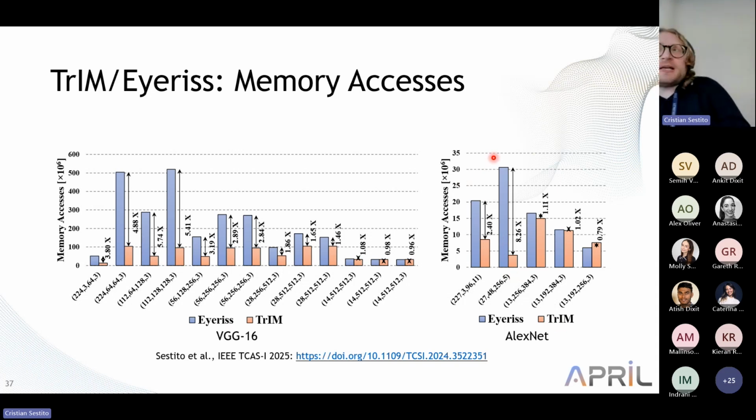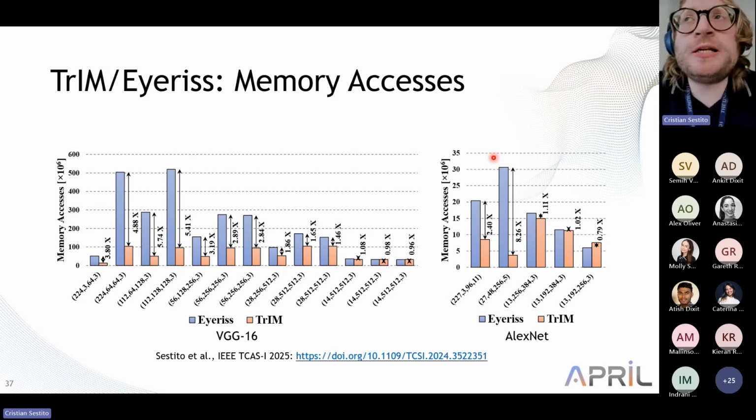So now this is an important consideration, and it is also proper to mention that the memory accesses that we report here are normalized memory accesses. So we're trying to take into account all the sources of buffering facilities, so external memory, global buffer inside the chip, scratch pads for Eyeriss at the processing element level, but all the numbers are obviously referred to the external memory access in order to do proper normalization of the data.